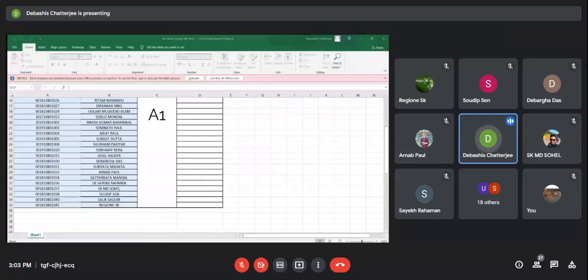The first step you will always find is to make the main dimensions, to design or to have a gross estimation of the main dimensions. So what are the main dimensions? In a rotating machine, the main dimensions are length and diameter. Now, D square L gives you an idea of volume. Normally you find that larger machines have larger volumes.